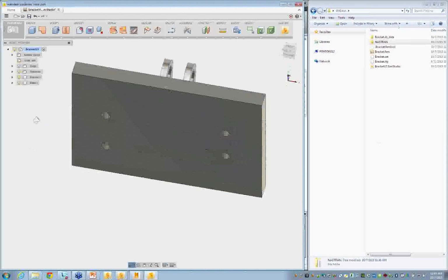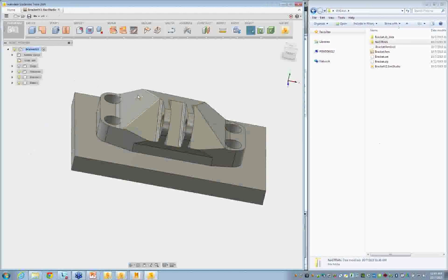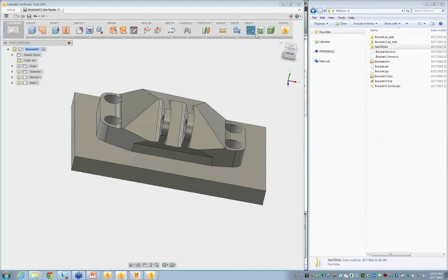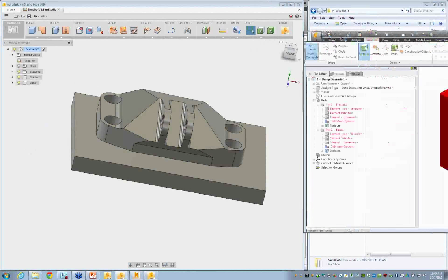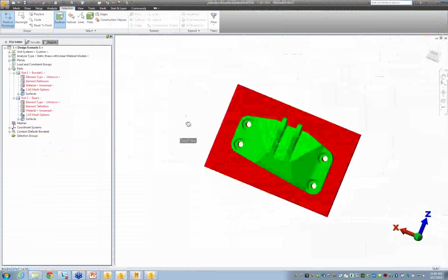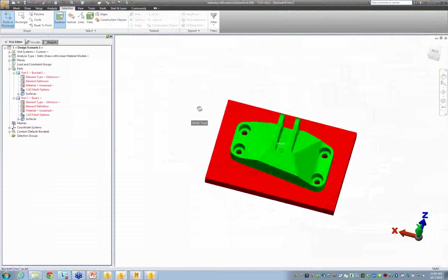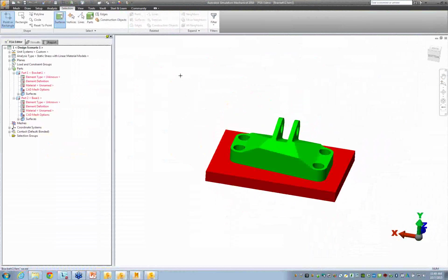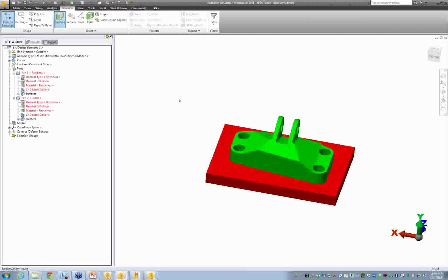All good so far. When I save this, I have this assembly of 2 parts, and I can push this into Simulation Mechanical. And in fact, it started to show up on my other screen, so I'll go ahead and merge it over here. So I have this 2-part assembly, right? And to talk about contact, especially in the case of Nastran, Nastran can handle contact regardless of whether you have a matched mesh or an unmatched mesh.